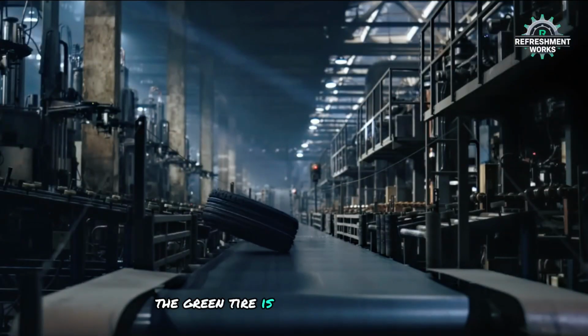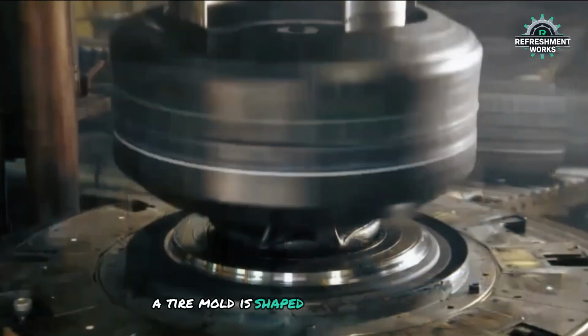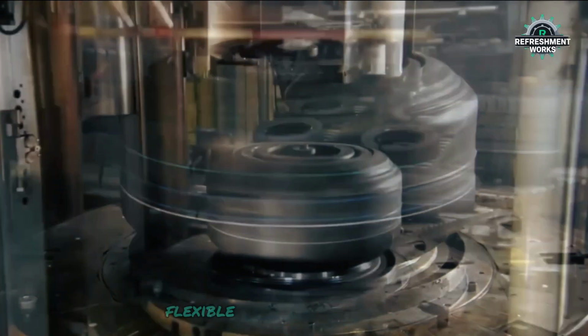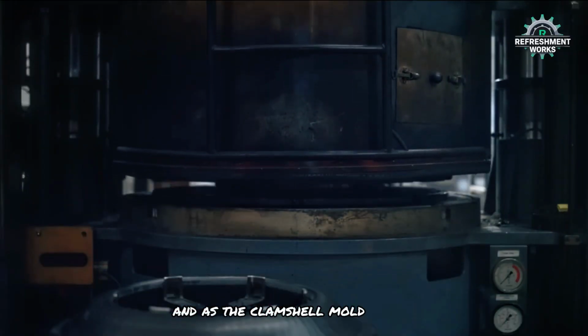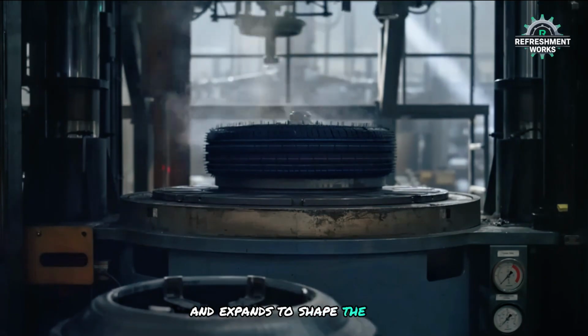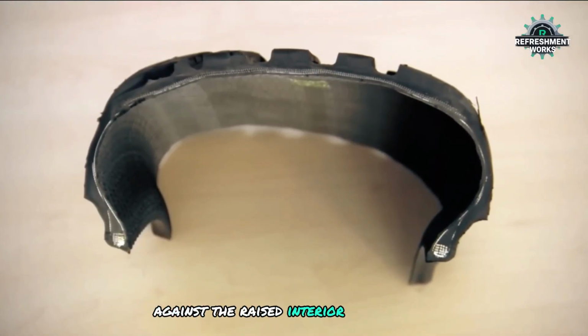The green tire is placed inside a large mold. For the curing process, a tire mold is shaped like a monstrous metal clam, which opens to reveal a large, flexible balloon called a bladder. This green tire is placed over the bladder, and as the clamshell mold closes, the bladder fills with steam and expands to shape the tire and force the blank tread rubber against the raised interior of the mold.